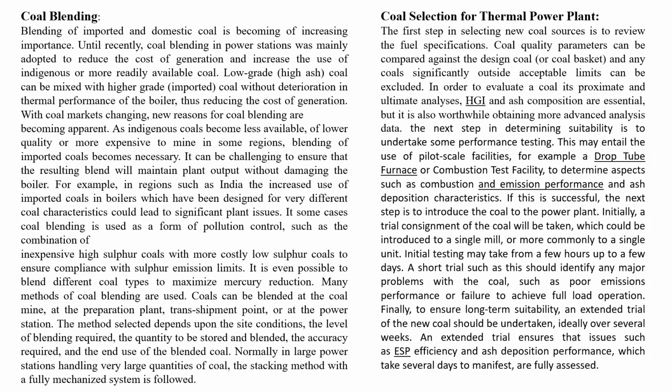Finally, you have to ensure long-term suitability. An extended trial of new coal should be undertaken, ideally over several weeks. An extended trial ensures that issues such as electrostatic precipitator efficiency and ash deposition performance, which take several days to manifest, are fully assessed. So this is about the coal.